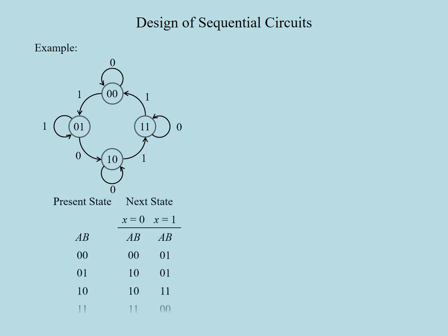We can tabulate the transitions defined in the state diagram in a state table. Here we call the state variables A and B, and the input X. From this state transition table, it is seen that there are no two lines that match for all possible next states and the output. That means no state reductions are possible. Let us obtain the circuit for the state diagram using JK flip-flops. Since there are 4 states, we will use 2 flip-flops.